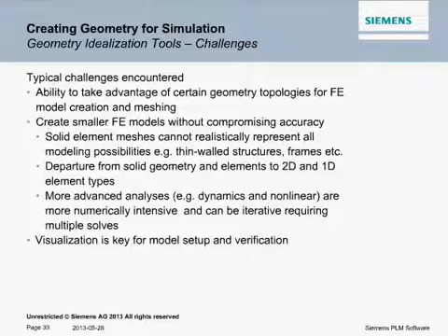Also, another point, when we get away from the solid geometry and using 2D and 1D elements, visualization, actually being able to see the model, becomes important, because if you look at just a model containing 1D elements, you want to be able to see it more than just a series of lines. You actually need to be able to visualize the actual underlying shape in order to make sure that it's oriented correctly and positioned correctly and what have you.